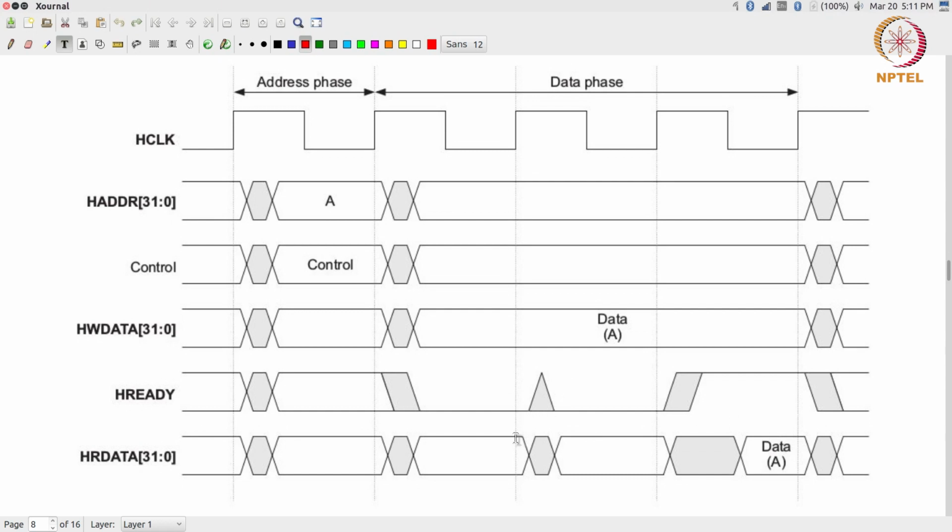Keep in mind that at the previous two clock edges, even though there might have been some data at those clock edges, they are not considered valid data. The master should not do anything with them. So, it is very simple: just use this HReady signal and you can insert wait states into the bus transaction as you want. Of course, what you need to be careful of is, if it is implemented in this way, one badly designed slave can effectively destroy a system by just pulling HReady low and leaving it there.